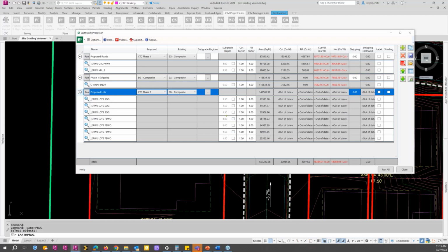They all have depth to them. Our full basement walkouts, when we preliminarily graded it for the back of these, we went down 7.5 feet. I'm going to push it down another 1/2 foot for our rough grading back there for these full basement walkouts. And then these 150 ones are the front of the walkout areas.